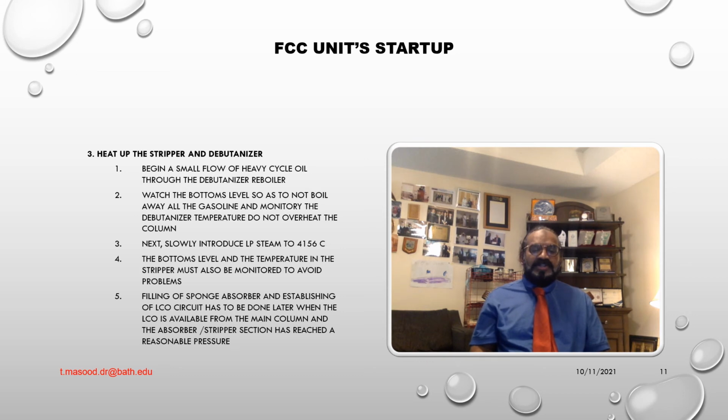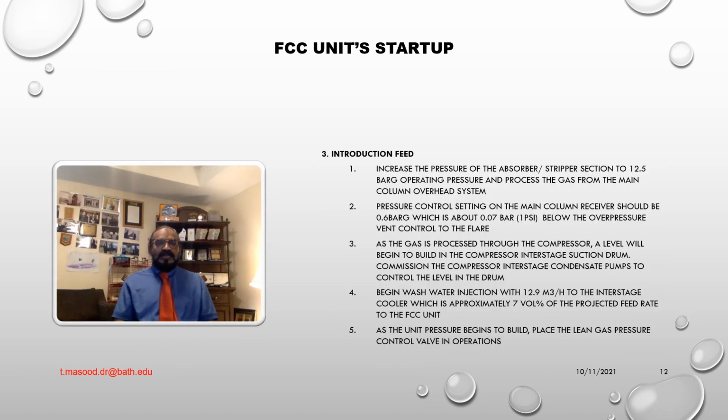Okay, next topic, introduction of feed. When raw oil is fed to the reactor risers, excess gas will be produced almost immediately. There will be a small delay of a few minutes until the liquid hydrocarbon feed to the primary absorber increases significantly.